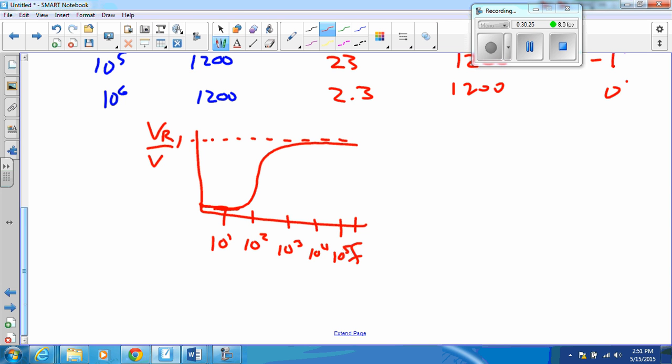So this is the high mid and high on the soundboard, right? That's exactly what it is. They are literally made with capacitors and inductors, or the digital equivalents of those anymore. And actually, honestly, they use a trick to use just capacitors in analog ones because inductors are kind of big and bulky. Capacitors are more convenient. So that's a 1, because the greatest voltage I could possibly get out of this is the input voltage, unless I have some kind of amplifier.